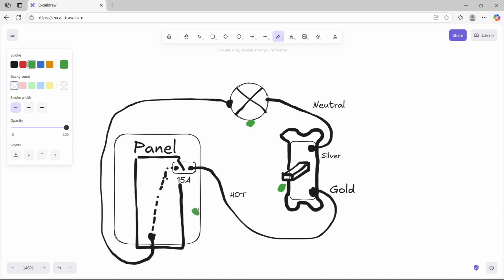And then usually either on the panel itself or on the bus bar, depending on the type of panel, you will have another little ground screw. And what happens is inside of the box in your wall, these two grounds will get pigtailed, tied together. And then you'll have a little wire coming and attaching to that light switch. So now all of a sudden, all three of these devices are grounded together back to your source, and that prevents any kind of shock occurring.